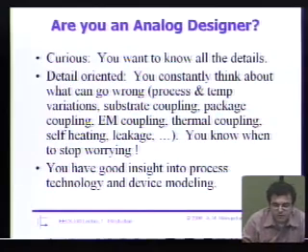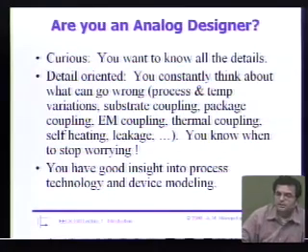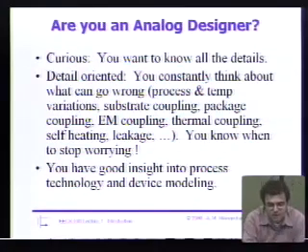Example of that in analog circuits is biasing, right? Now, my students, and I know a lot of you guys out there, when you design circuits, you think, oh, I'm in a university environment, for biasing I'm just going to take a pad out and I can bring in my external bias, right? So you're lazy. You don't spend time doing a good job on the biasing. And a lot of times you get burned because you pick up noise on that bias line, or it turns out to be really noisy, so you have to go out and buy a really low noise bias source.